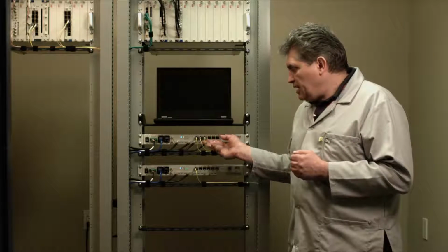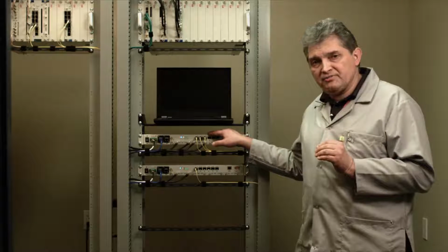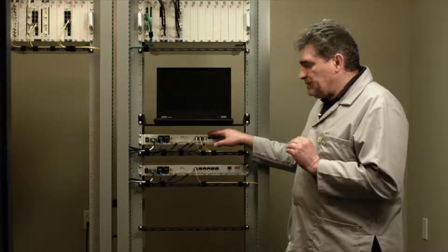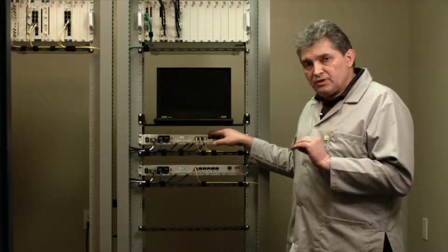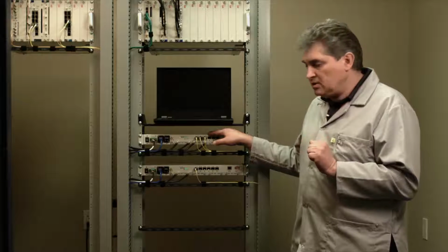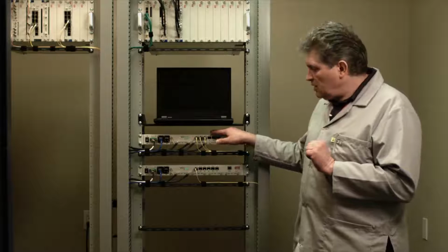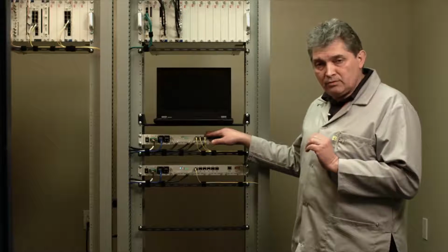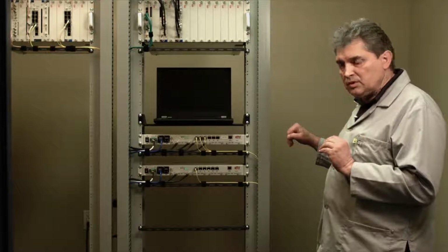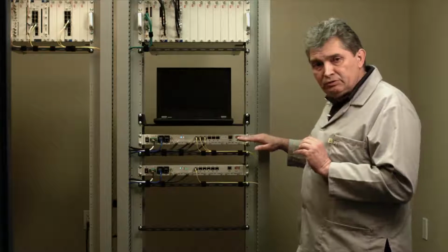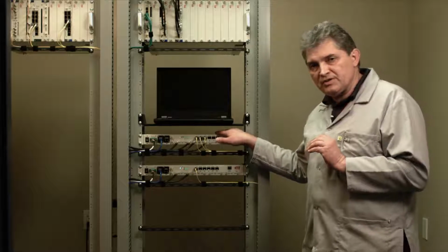What is currently inside the T-host unit is a so-called bidirectional SFP, meaning that it has a built-in optical duplexer, demultiplexer, and operates at two wavelengths. On downlink wavelength 1, the signal is sent from a host unit to a remote. On wavelength 2, the uplink signal is received from the remote and processed inside the host.